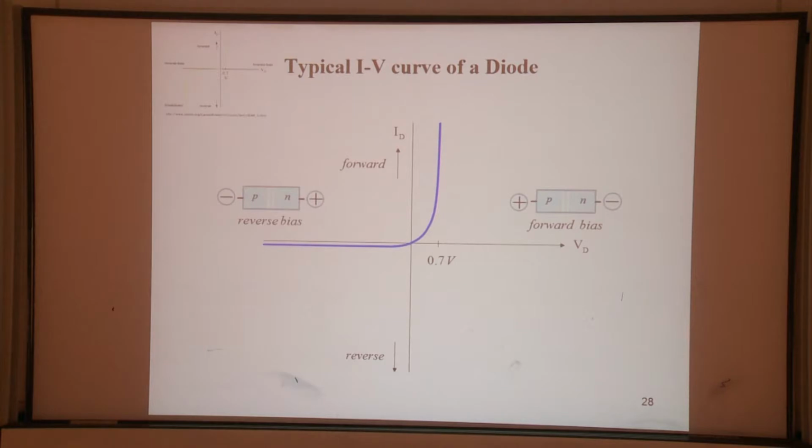And the limit is controlled by the difference of the Fermi level. Actually, the barrier. We can always reduce the barrier, but we will not be able to overcome the barrier. When we reduce the barrier to 0, then the current will go to infinity. That means this is a barrier, and it will not exceed the barrier. So there will be a limitation. Usually, for a silicon PN junction, the barrier depends on the band gap. So usually for the solar cell, this will be around 0.7 volts. All right, but I'll go into more detail afterwards.